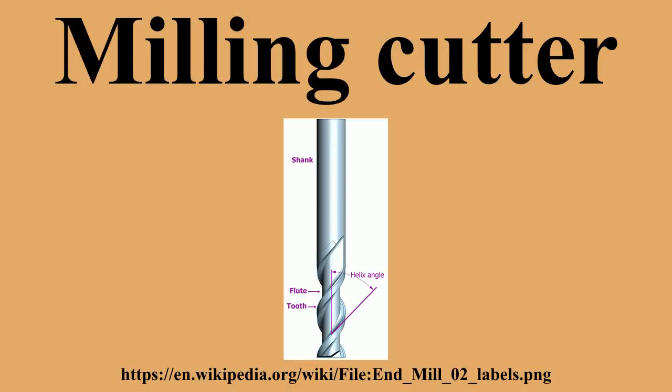A finishing cutter may have a large number of teeth for removing material carefully. However, the large number of flutes leaves little room for efficient swarf removal, so they are less appropriate for removing larger amounts of material. Coatings.